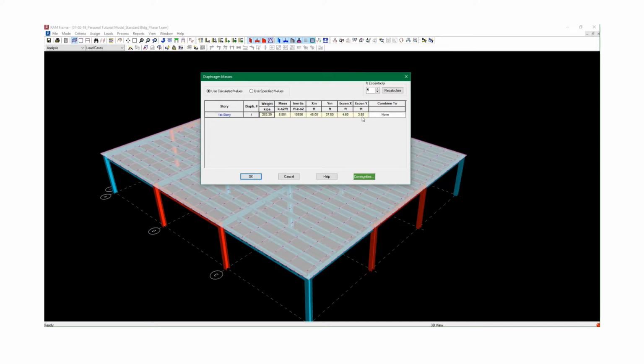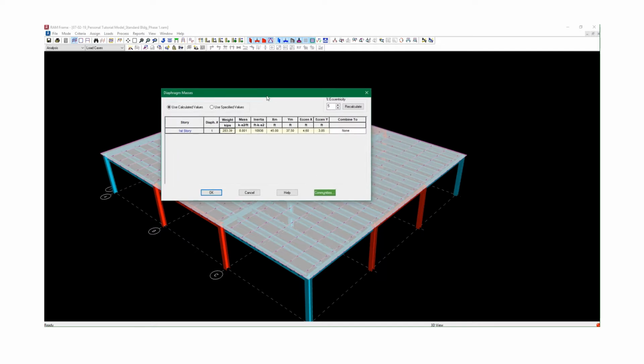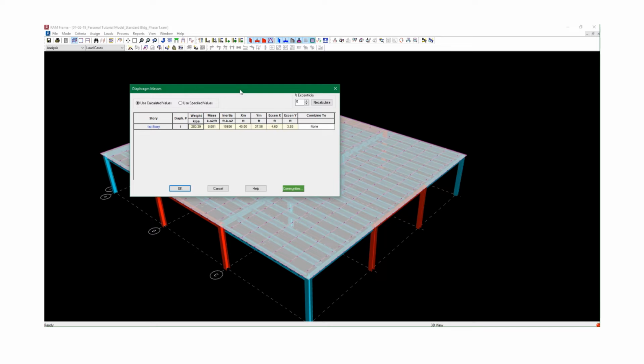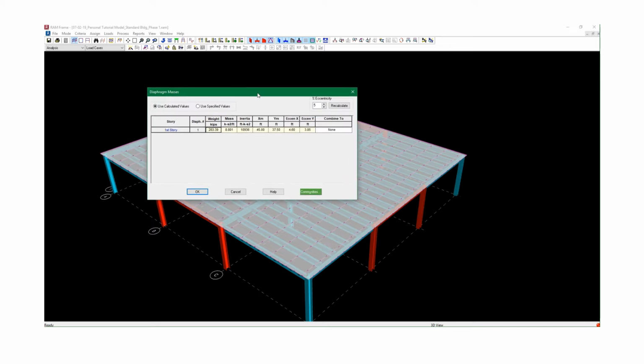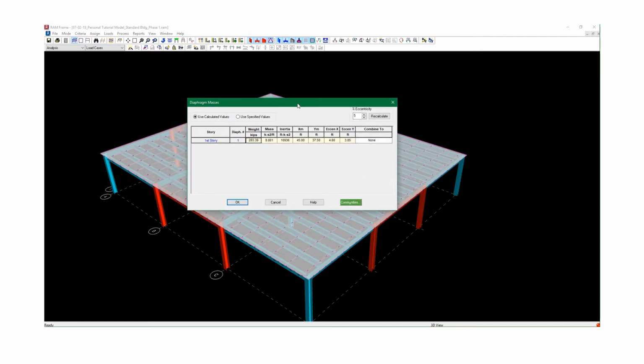According to these calculations, you should do hand checks to verify this information. I've done it in the past, and it's very accurate. However, as you get into the details of modeling structures in the real world, you want to do your best to validate that accuracy as much as possible. You still have to pay attention to this, but in general, you can trust RAM that this is right for most structures.